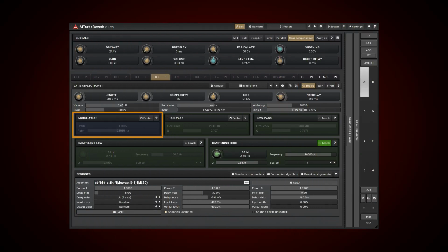The modulation pane contains parameters controlling the modulation of an input signal. If it is off, the generator receives the input signal in its original form. When the modulation is enabled, the input signal gets modulated by a built-in low-frequency oscillator. Commonly, it is used for reducing a comb filter effect, appearing as the summation of an original and its delayed copies.